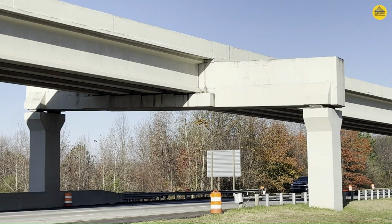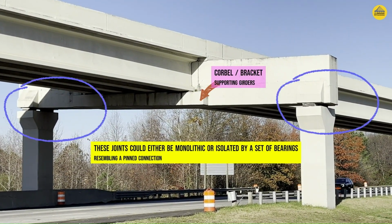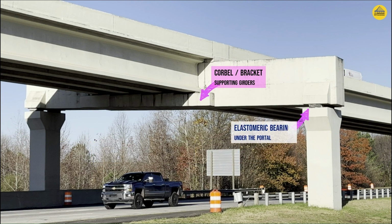Now let's go back to our structure and see which option is adopted. It should be clear that option number 2 is adopted in this case, as the girders are placed within the portal cap and not on top of the portal cap. Also observe that there are gaps at the ends of the portal cap, right between the portal piers and the cap, which means that this connection is not monolithic, and now we will see how it is obtained.